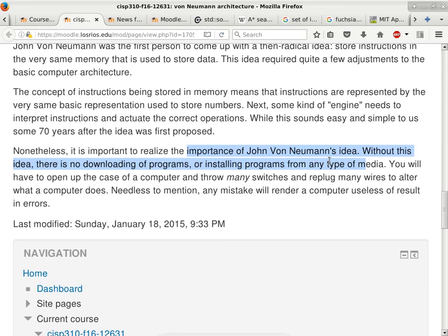So this is also called just PROM, for programmable ROM, but it implies it is one-time programmable. At some point, people came up with the idea of EPROM. E stands for erasable, so this is erasable, programmable, read-only memory. These are the ones where you see a little optical window in the chip, usually in the form of a circle that is transparent.